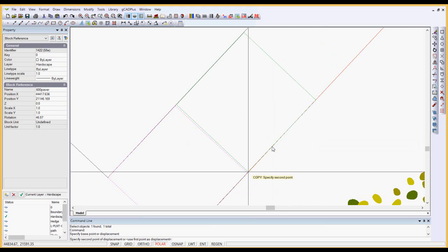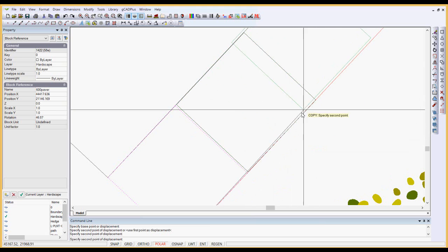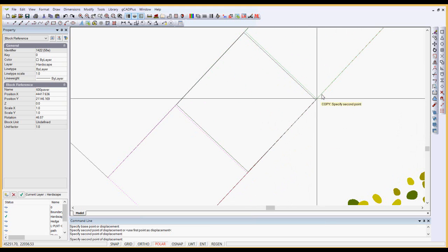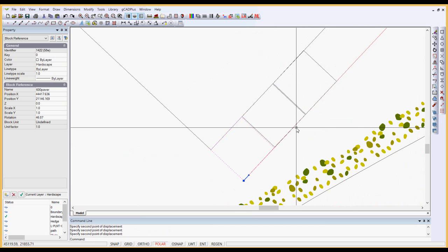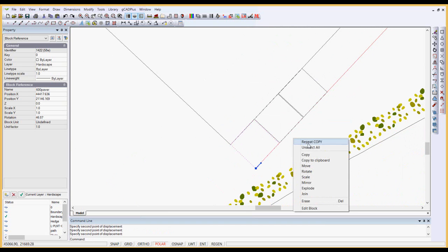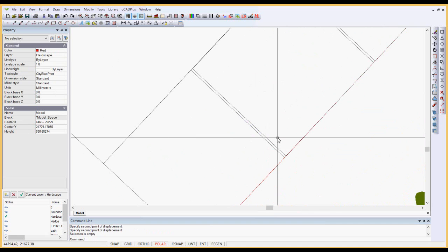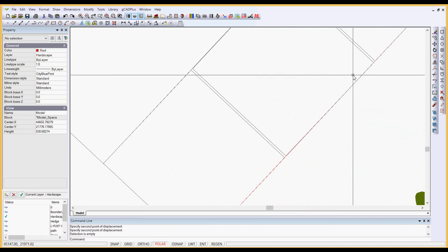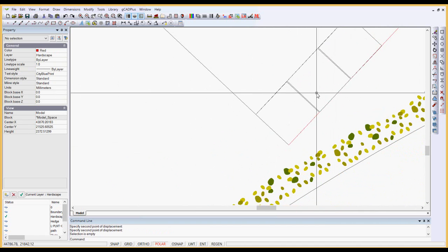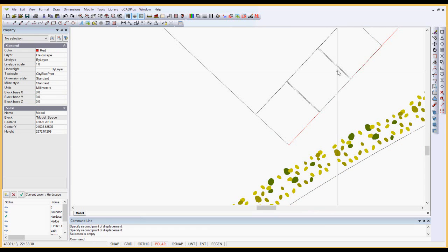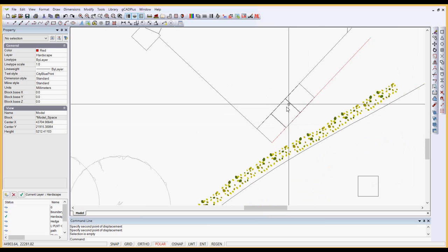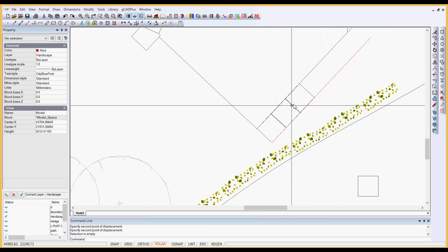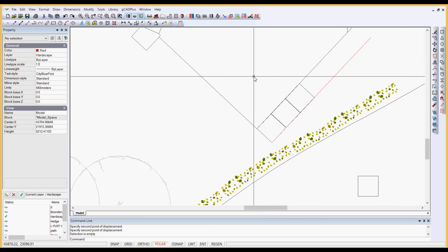And you see how things click into position, and then we go click again, and I'll finish and just zoom out a little, unselect all, and just zoom in. We've now got a precise 10mm gap between each of the paving bricks, and the paving bricks run neatly along. So it's going to be a relatively simple matter to align them correctly along that line.